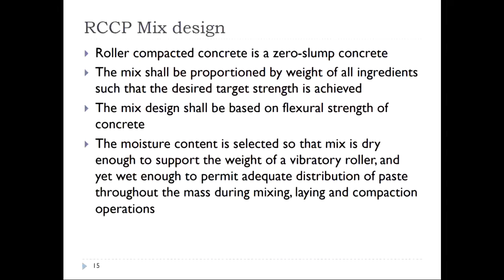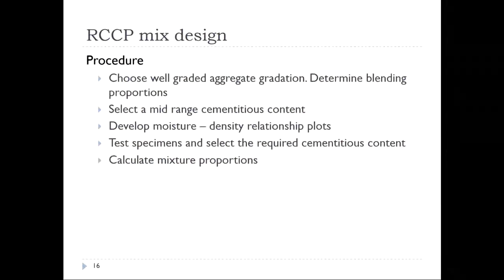Now the moisture content of these mixes is determined from your Proctor test. But when it comes to the site, you need to do a correction based on the moisture content of the aggregates. So you cannot directly add whatever moisture content you determine in the laboratory when it comes to the site. So these are the different procedures.